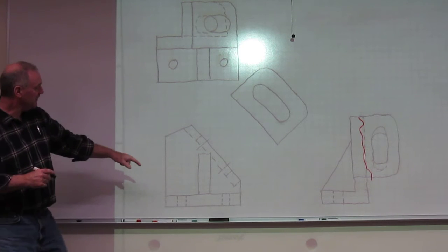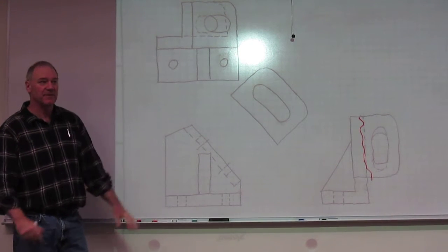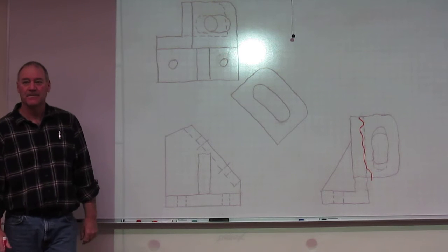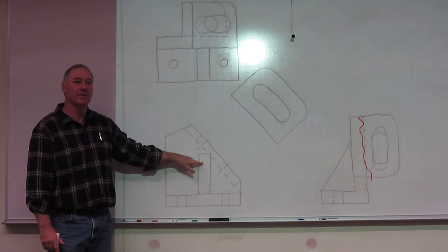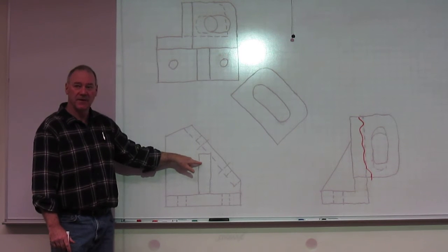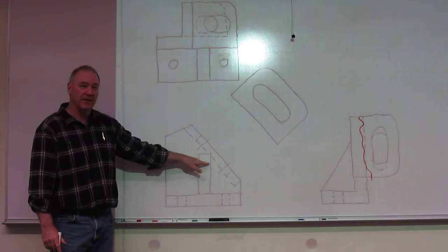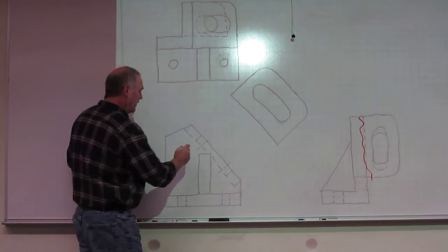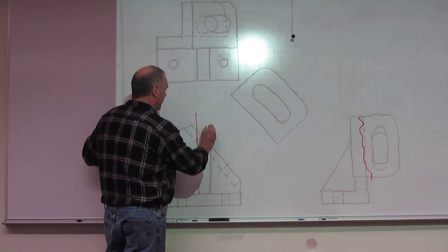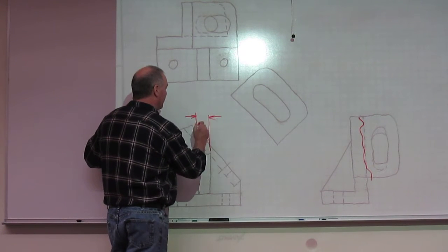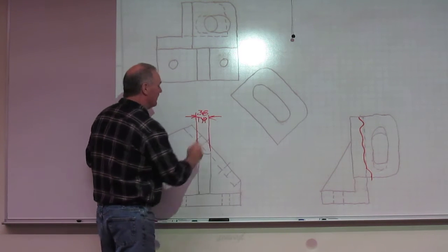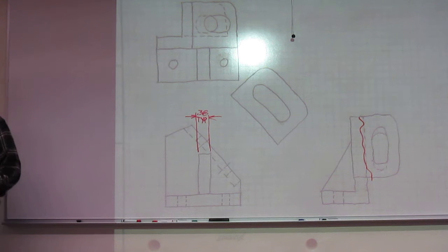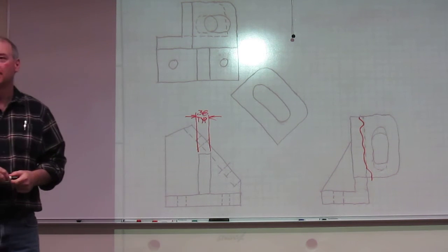Now, where do I handle the thickness of these plates? Back to the original. I really think the only good view you've got of it is right here. The only good contour view. So in essence, I would probably be looking at throwing it right here somewhere and taking advantage of this note. We really haven't had a chance to use it yet, but here's a good chance to use it. Okay, 0.38 TYP. This is a perfect illustration of what we use typical for.